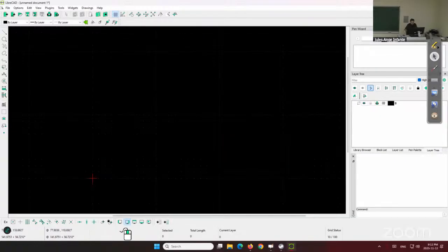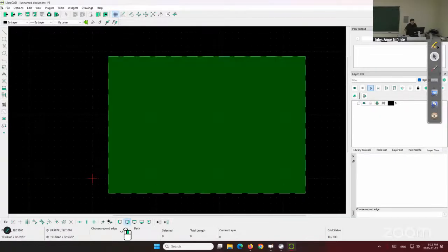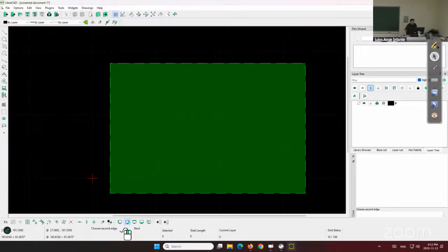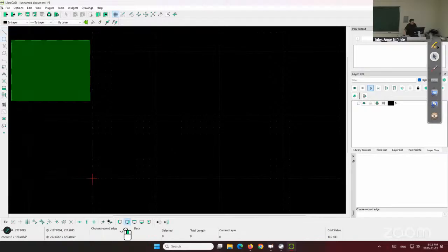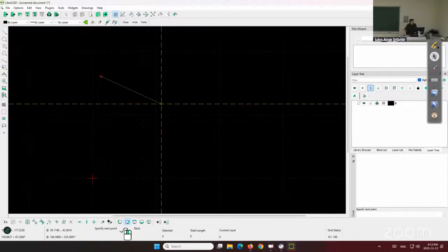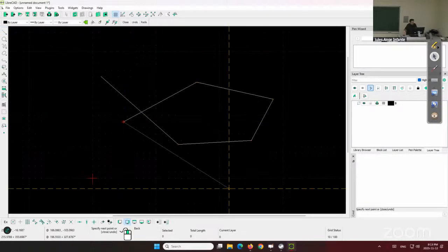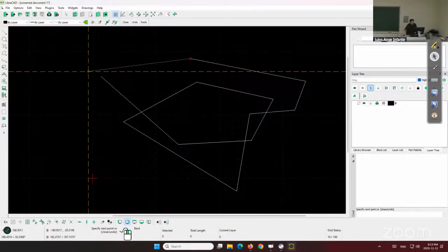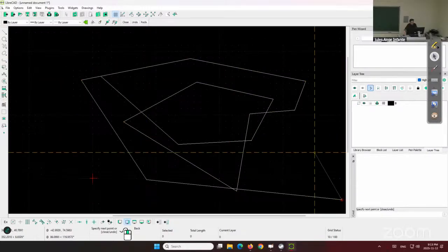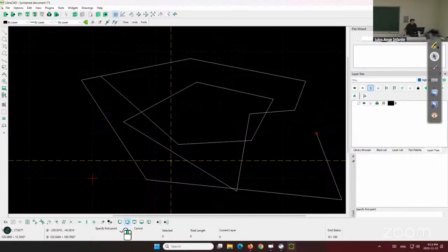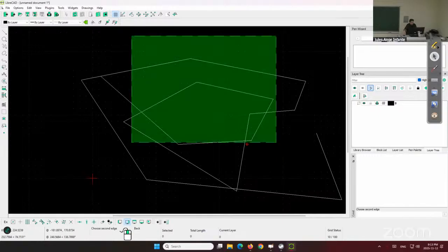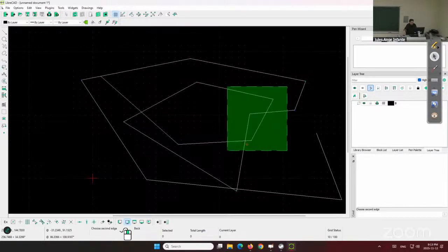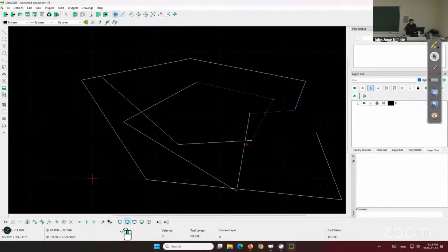The selection works the same. Going back, you get the crossing selection. This is a full enclosed window selection. So if you're not familiar with the selection mode, so here you have the tools to draw lines. It's much easier to learn how to use than AutoCAD is, but it's also much, much more limited, right? But it's still pretty powerful in what it does. So if I want to select like this, everything it touches gets selected. If I select this way, only what's fully enclosed gets selected, just like in AutoCAD.